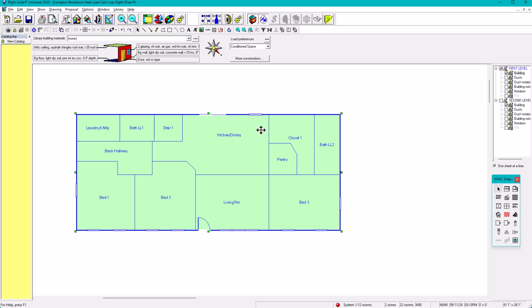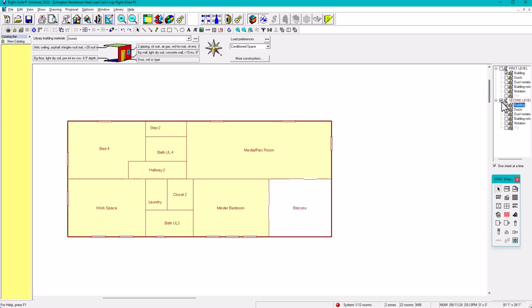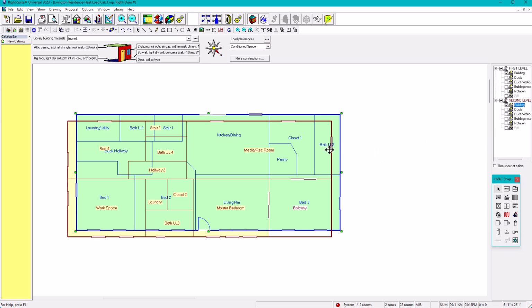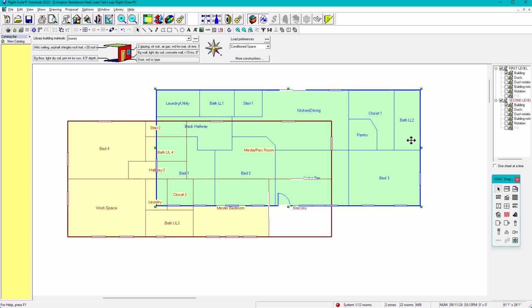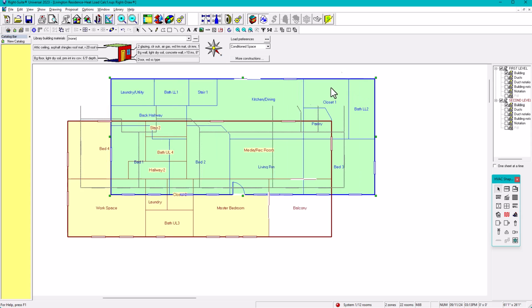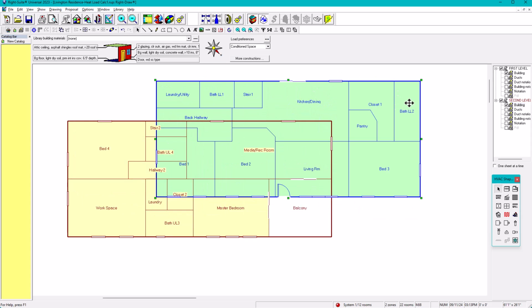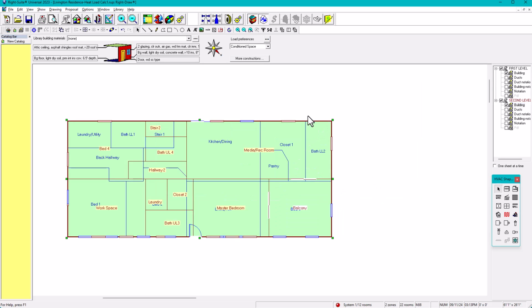Okay, so again, for grouping, now you have only one selection tool in here. See, if you go here, it's selecting only one. Okay, number one application, why this is very important. If you want to line up your first floor and second floor, you can group both. For example, let's go checking here. Right here, like that. Okay, how do you know they are lining up? For example, in this case, they are not lining up. When they are grouped, you just have to select one and you are going to be able to hover over it, right? So in this case, what I could do is just line it up. So now all the building is lining up, all the floors, all the levels.